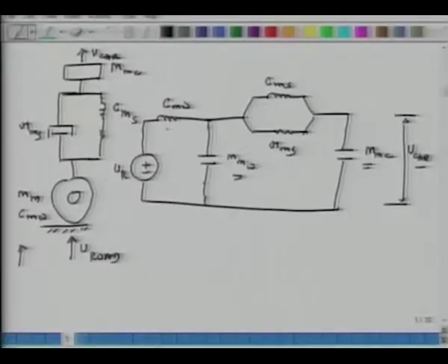As frequency goes up, omega goes up, and the impedance offered by that inductor, which are these compliance members, keeps on going up significantly, and at very high frequencies it becomes closer and closer to an open circuit. For a capacitor it's just the inverse, because the impedance is 1 over omega C. So at low frequencies, it behaves more and more like an open circuit, and at high frequencies it behaves more and more like a short circuit.